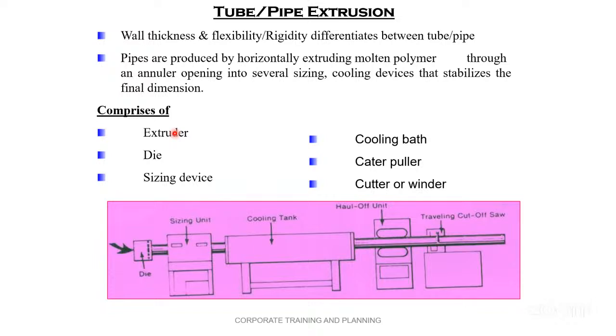In the straight through die, the material flows in a straight line, making an angle of 180 degrees, between the extruder and the inline equipment. So friends, you could see the inline equipment and straight through dies where the material flows at a 180 degree angle.